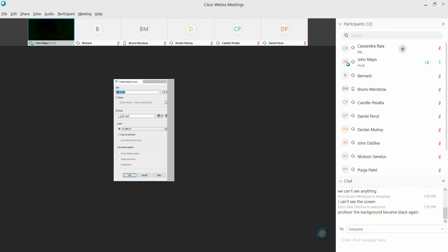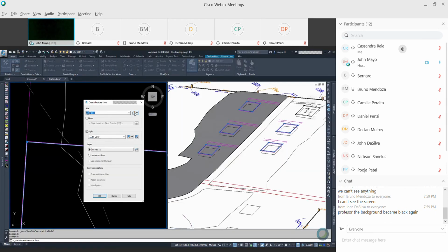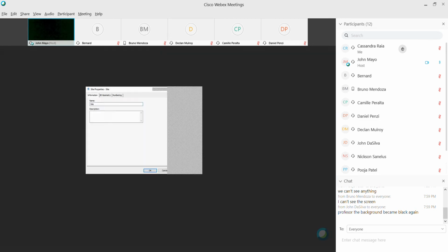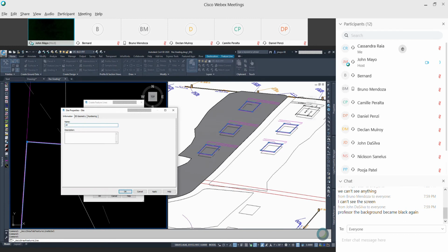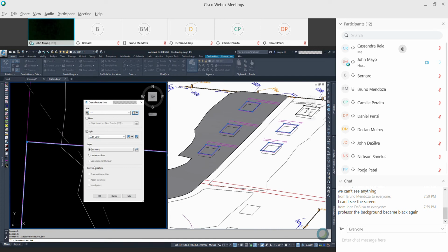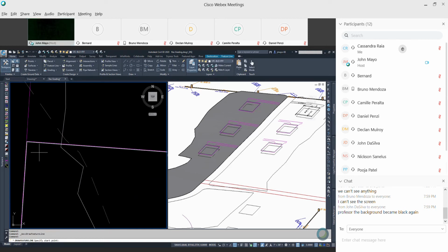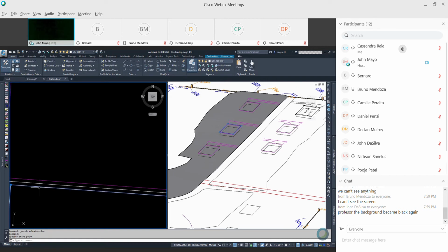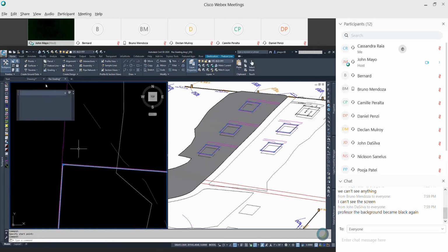So I just convert them all. I get a new site temporarily because my site is what creates my layer. I'm going to call this first floor. Finish first floor. Style can be by layer, and I don't want the elevations assigned. And I've got that layer. Oh, wait, that was draw. I had the wrong command. I'm sorry. So here's my polylines again, select it again. What I did was I went create feature line, not create feature line from objects. That's the one I wanted.